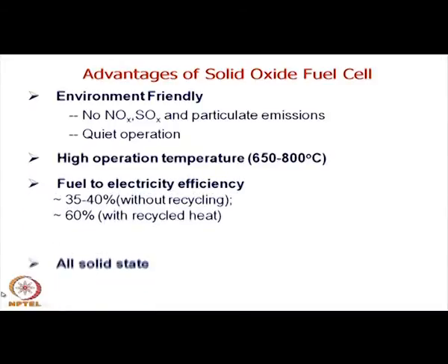complete our discussion for this class with the specific advantages of fuel cells, solid oxide fuel cell in particular. This is environment friendly in the sense it does not produce NOx, SOx and particulate emissions, and has quiet operation, which is true for many of the fuel cells. High operating temperature is an advantage in some cases, because the kinetics of the process is very high. So, one can draw very high currents.